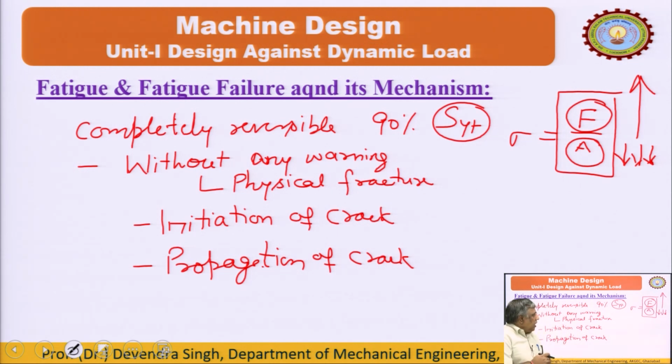this stress, and somewhere this stress exceeds the strength of the material, and it may take place inside the material. This crack may be a scratch caused by machining. It may be on the surface, it may be material defects and discontinuities, where this crack will be considered as the initiation point, and further it will be propagated.